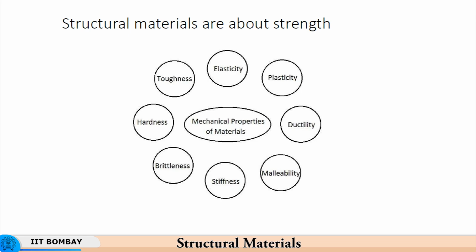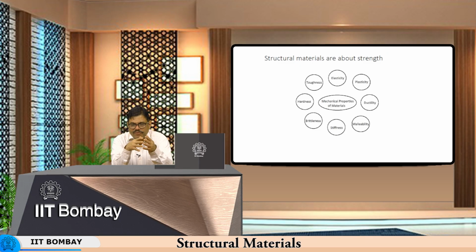In spite of removing the load, the material continues to remain bent at 35 degrees, which means that there is a permanent deformation taking place, and that is the result of plasticity. Now, to what extent can you deform things permanently? Can you change the shape to a large extent permanently? Then that would mean it has high ductility.